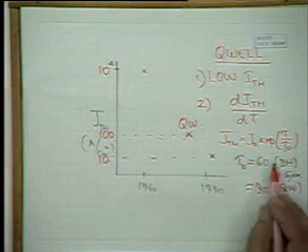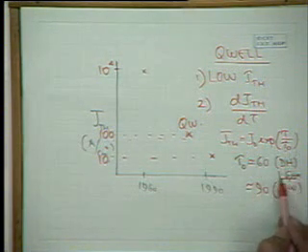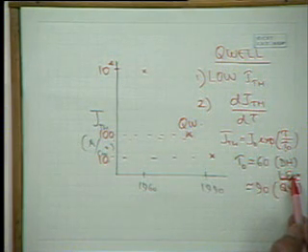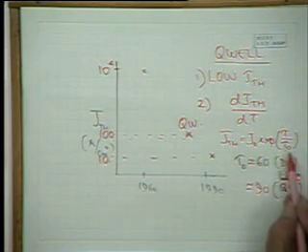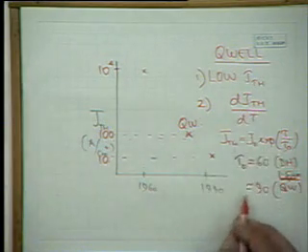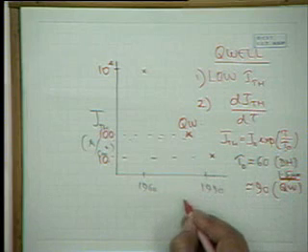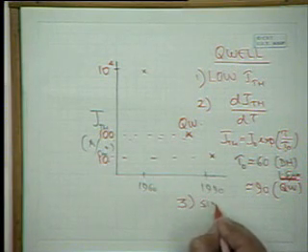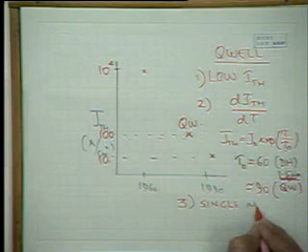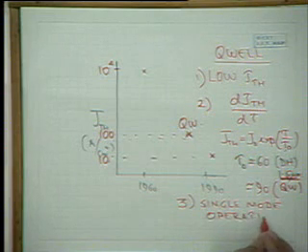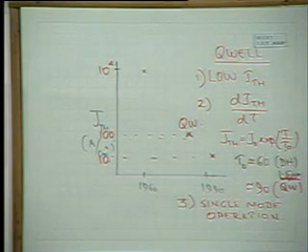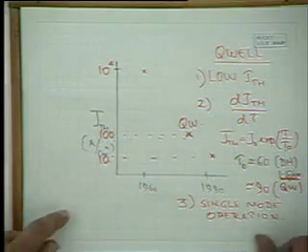And we know that these values depend upon the wavelength of operation. Why? Because at a longer wavelength, the band gap is less, so the temperature dependence is more. In the quantum well laser, the temperature dependence is less. Also, we can have single mode operation. In this case,